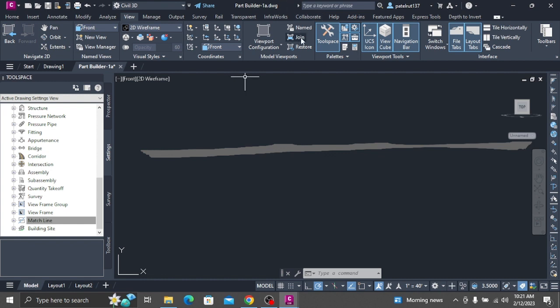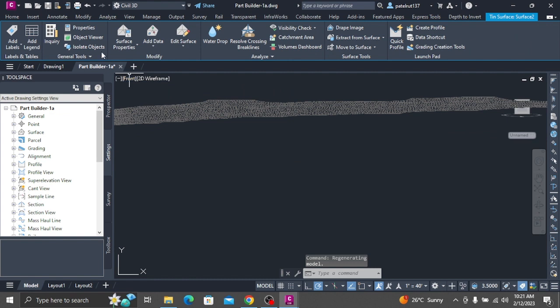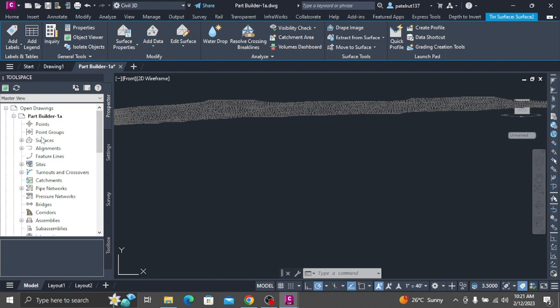Right-click Rim Add Dimension Distance. Click 2 points at either end of the top side of the outer rectangle. Repeat these steps for the right side of the outer rectangle. Repeat these steps for top and right sides of the opening, in that order. Reposition the dimensions as needed so that they are easy to read. Len 3 and Len 4 are created for the long side and short side of the opening, respectively.